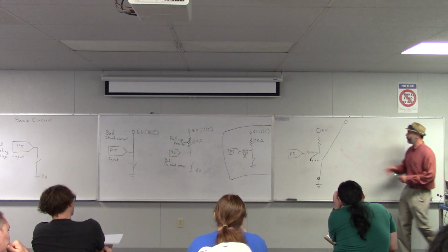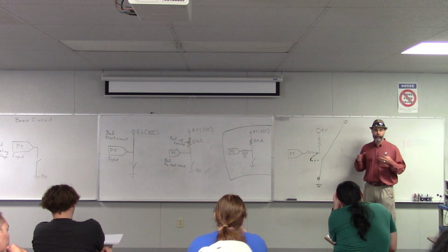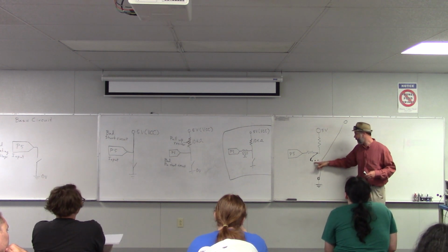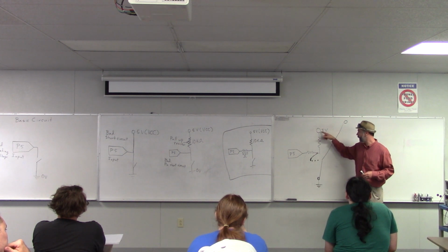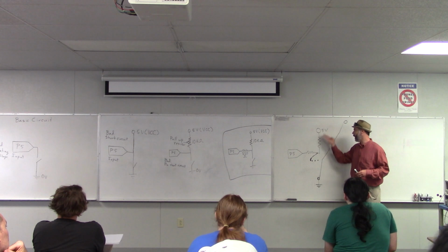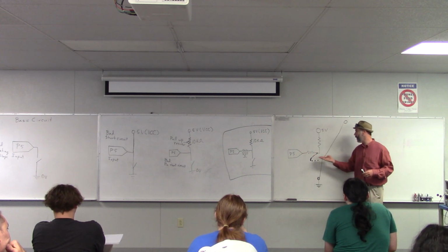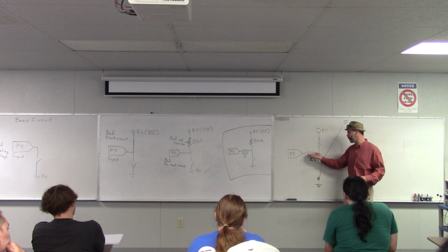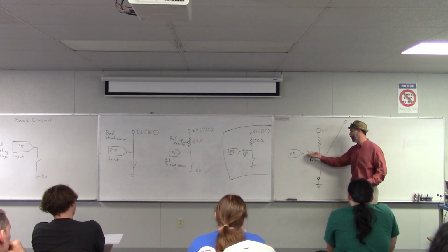When you're in the normal driving position and there's nothing touching the Whisker, it's kind of sticking out like this. And so you've got this pull-up resistor that's pulling your pin voltage up. So what is your pin voltage when you're in the normal driving position? 5 volts, exactly. So you're driving along, you should see 5 volts there, high voltage.